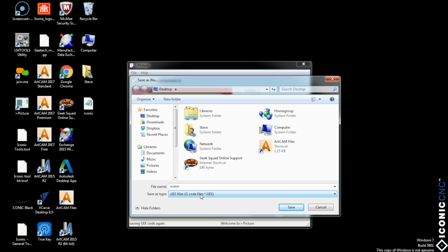It eliminates a couple of problems. One of them is the missizing of a piece of material. So I designed a project, in this case 12 by 12, but inadvertently I put a piece of material 8 by 8. And of course that's problematic because the project thinks the material is 12 by 12 and it's going to machine outside the border of the material size.